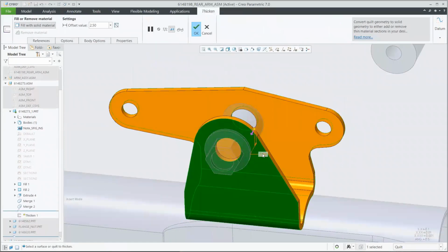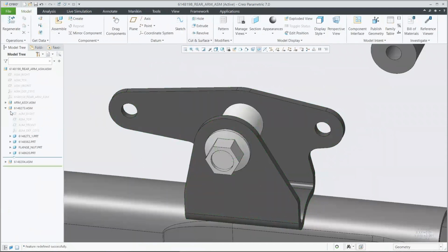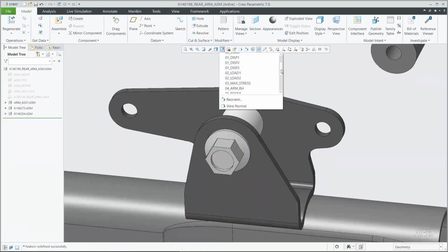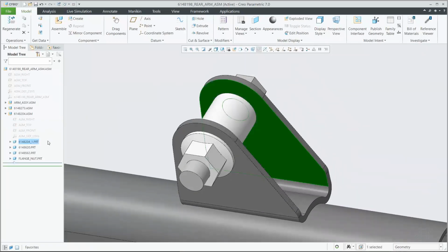This could mean increasing the length of the bracket here to spread out the stress a little bit. Another thing that I could try is increasing the thickness of the bracket just to make it stronger overall. A couple different options that we could go through and focus on there. Let's move over and do the same thing on our other bracket.